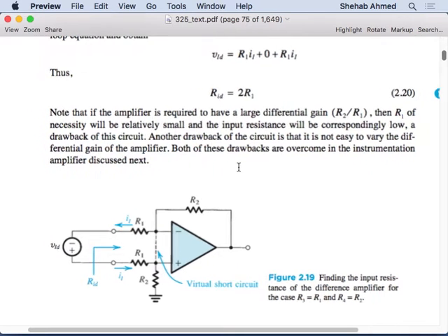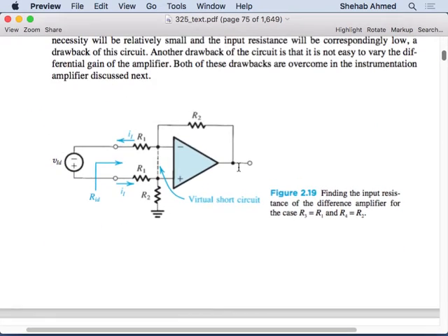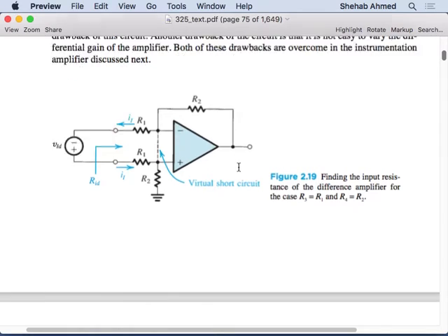So we went away and said, okay, fine. This is a nice circuit. It does some nice stuff for us, right? It affects the difference of the input. It allows us to look at the differential signal, not a single-ended signal, right? It's a nice system from that perspective, and it has a way to deal with the common mode voltage somehow, right? But it has these limitations.